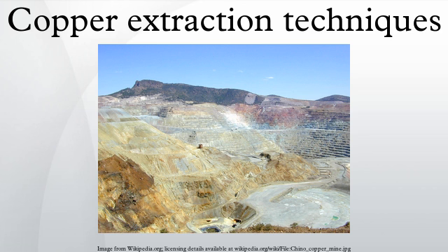The ore is then wet, suspended in a slurry, and mixed with xanthates or other reagents, which render the sulfide particles hydrophobic. Typical reagents include potassium ethyl xanthate and sodium ethyl xanthate, but dithiophosphates and dithiocarbamates are also used. The treated ore is introduced to a water-filled aeration tank containing surfactants such as methyl isobutyl carbinol. Air is constantly forced through the slurry and the air bubbles attach to the hydrophobic copper sulfide particles, which are conducted to the surface, where they form a froth and are skimmed off.